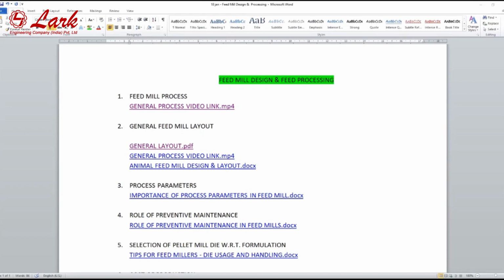Even in Haryana, with the help of stackers, feed millers are utilizing stacking height up to 30 feet, getting the maximum efficiency from their warehouse storage. So generally, we multiply the raw material requirement by the factor of 6. That will be the total square feet of the warehouse. But now we have to calculate the width and the length. We got the complete 42,000 square feet of the warehouse, but what will be the length and the width?